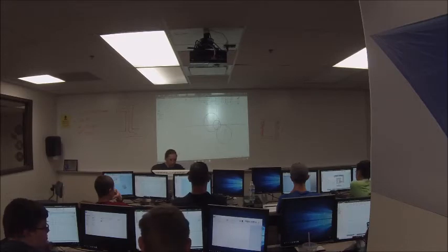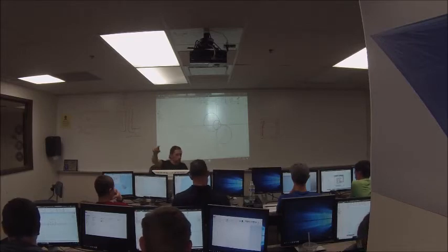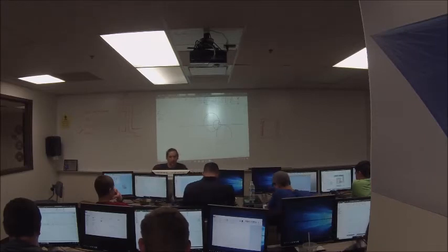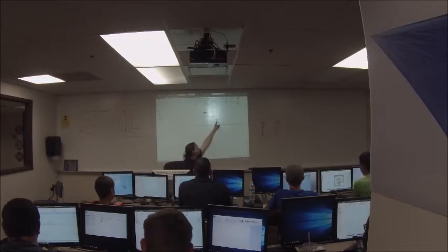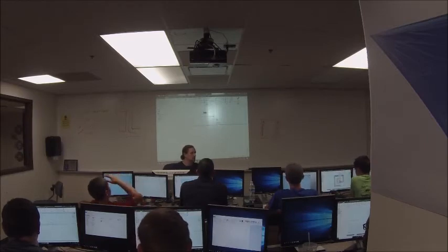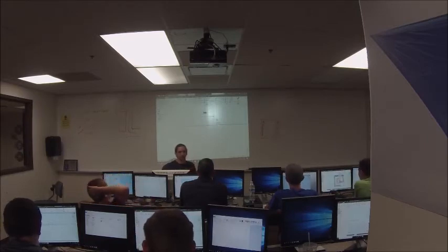Okay, so by default, Inventor places a few constraints automatically just by when you're clicking and placing lines or placing circles. It will create some things automatically. When you're creating lines, you can see here if I click and I keep it to the side, you see this little symbol right here? This little symbol means that it's going to automatically place a horizontal constraint on that line because the line is horizontal when I'm placing it.